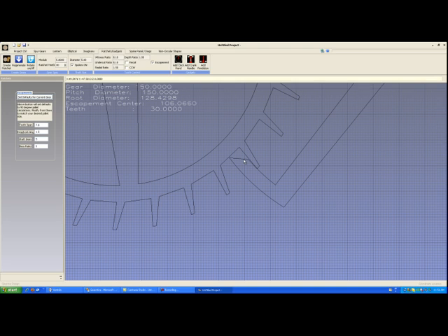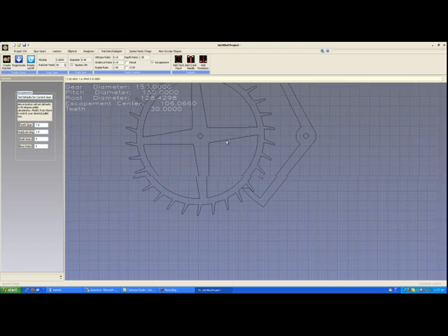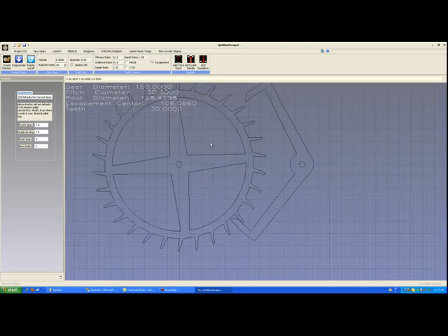The whole idea of the weight or spring that's driving a clock is to have just enough energy to keep that pendulum swinging so that the teeth hit the lock face at a good angle and she keeps swinging. As the gears in the clock get dirty, this relationship will change, and cleaning your clock's gears will bring it back to normal.